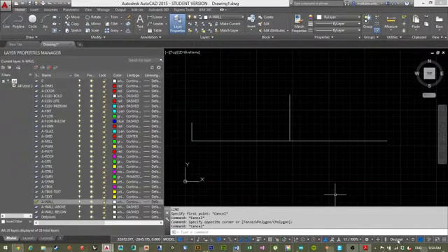This is the unit. So it never actually says metric within AutoCAD. That's part of the confusing part. But this is set up to be metric, and we're on decimal. Architectural is feet and inches. So if you had opened up that template and I drew a line, you'd see it would be like 6/32 of an inch or like 1 foot. So you would do all your dimensions that way.